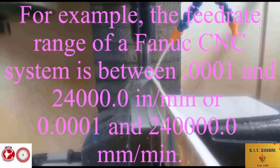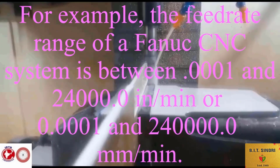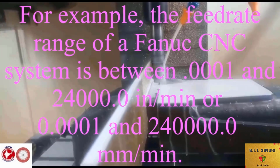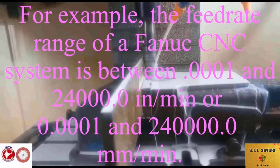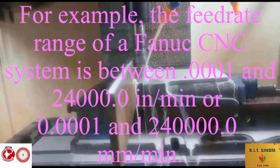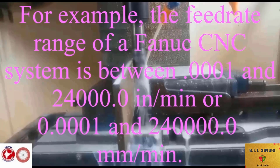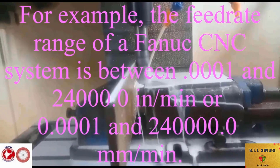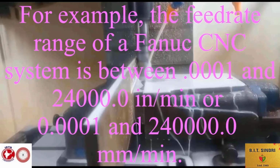For example, the feed rate range of a Fanuc CNC system is between 0.0001 and 24,000.0 inch per minute or 0.0001 and 240,000.0 millimeter per minute. Note that the difference between the two units is only a decimal point shift, not an actual translation. In programming, only the feed rates that belong within the specified range can be used. Such a feed rate will be smaller than that for the control system.